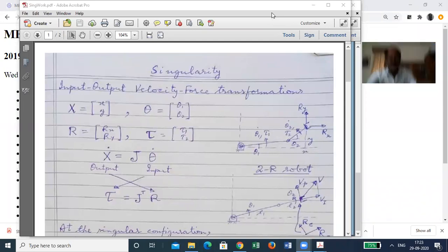Okay. So with this 2 degree of freedom planar robot, we will be in a position to study the idea of singularity easily. The end effector coordinates, that is task space coordinates, will be x and y, that is position of this point. It is only 2 degree of freedom, so we are not talking about controlling theta also. Only two output coordinates you can control with a 2 degree of freedom manipulator.